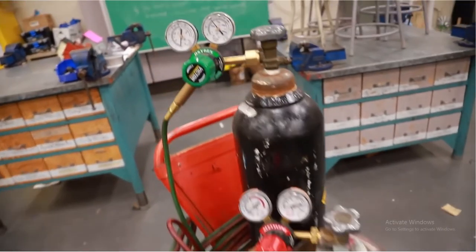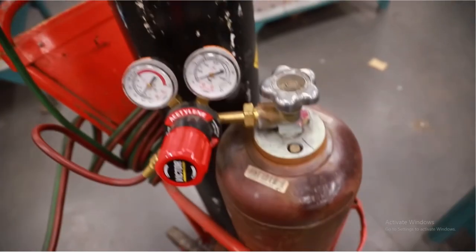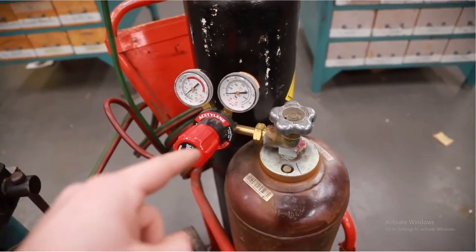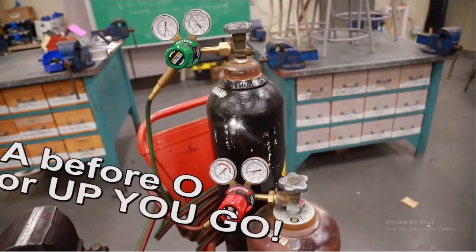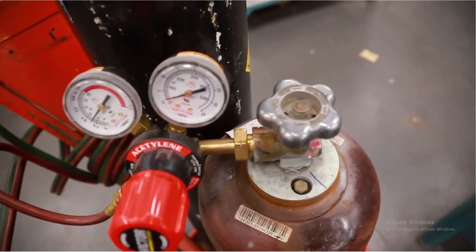So first off, setting up your tanks, we've got two here. We have an oxygen tank and we have an acetylene tank. I have a little rhyme that I follow for all of these steps. It's always going to be A before O, acetylene before oxygen, or up you go. Don't ask me why, but it's going to help you remember every single step.